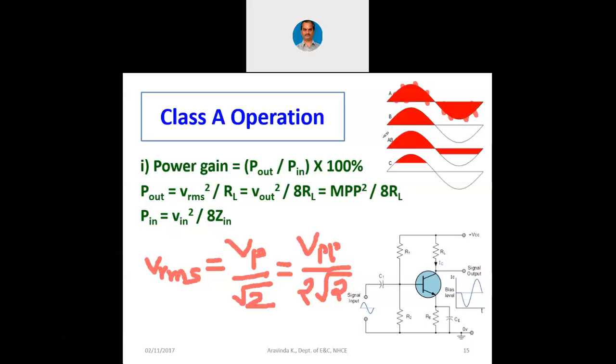Take samples, square them, then take a mean, take a root. It is in the reverse order there. Square, mean, root. But we call it root, mean, square, RMS. They have been writing it from the beginning like this and we have been telling it like that. Otherwise it is SMR. First take the samples, then square them, then take the mean of the squares, then take the root.